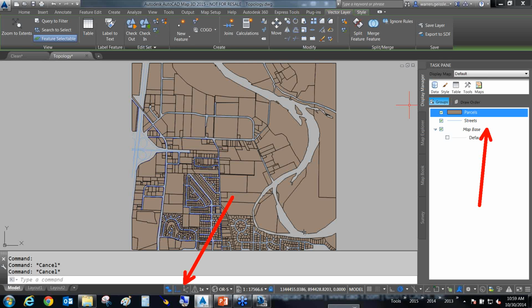Going into 3D orbit is not going to work terribly well. You need to use this button to actually build that in there, and as soon as you do, the program will automatically overlay the aerial imagery on top of the digital elevation model.